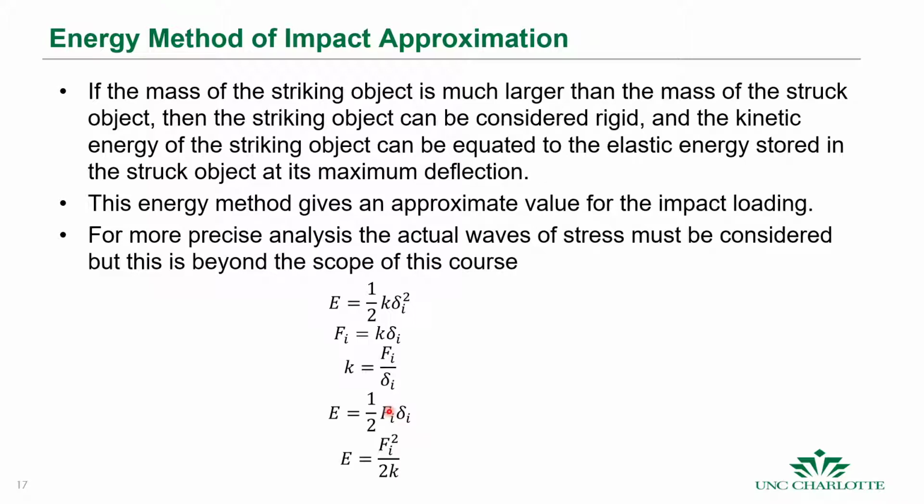We have the stress strain diagram. We have Young's modulus, which tells us the relationship between stress and strain, and it's a measure of stiffness of a system. We can also rewrite and express the energy in terms of the applied force squared over twice the stiffness just by playing around with these equations. Okay.